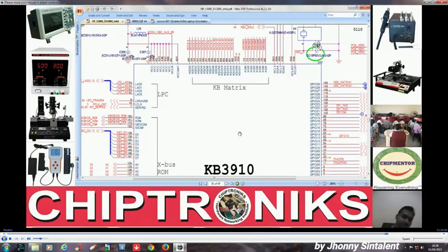So when we press a key on a desktop keyboard, what happens? It closes this circuit, it gets grounded, so the circuit is completed. A current goes to the 8048 keyboard encoder, and for each key it will generate two codes, a scan in and a scan out, and those two data are transmitted by the keyboard encoder via the PS2 interface to the IO controller, right?